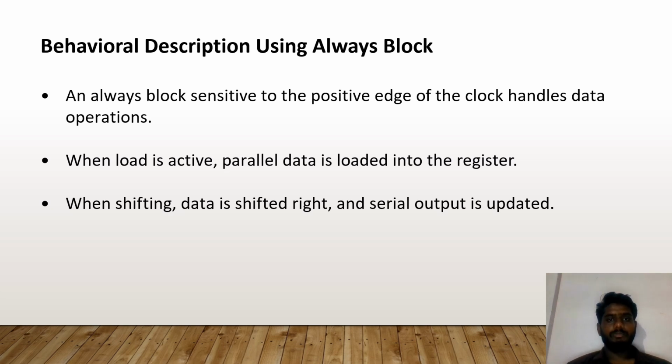Behavioral description using always block. An always block sensitive to the positive edge of the clock handles data operations. When load is active, parallel data is loaded into the register. When shifting, data is shifted right and serial output is updated.